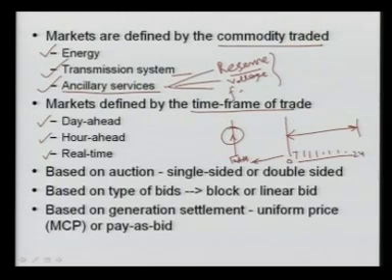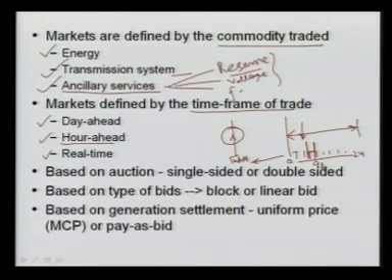Another market is the hour ahead market. If we are talking about 9 a.m., then at 8 a.m. we again forecast the 9 a.m. load, because there will always be error in the forecasting. So given the actual demand one hour ahead, we can also ask some generators to participate in this market. They should bid what rate they are going to sell power at in this hour ahead market. So this is called the 1 hour ahead market.